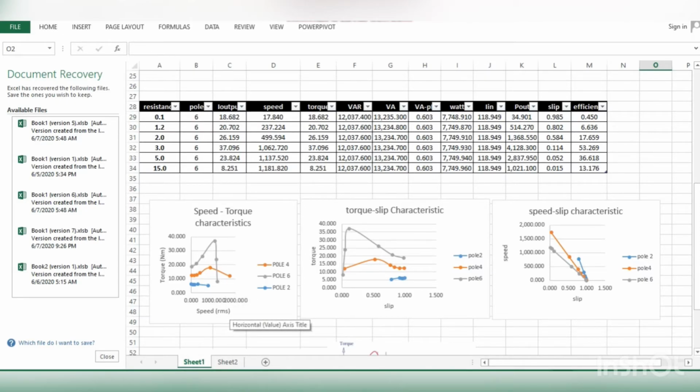Each has normal starting torque, high starting current, and low operating slip. They are useful. The load torque is low at start, so that full speed is achieved quickly, thus avoiding the problem of overheating while starting.